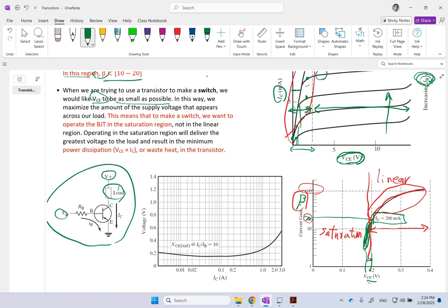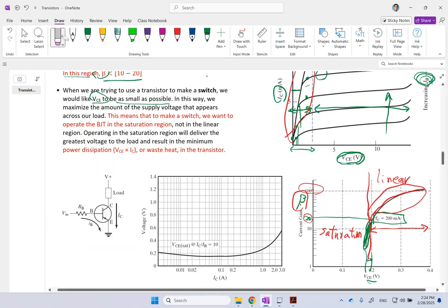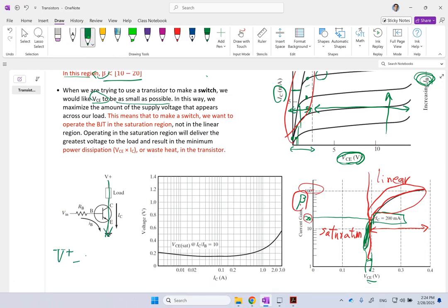You see that you're doing a low side switching with an NPN transistor. And if you look at this path here from V positive to 0, you can see that V plus minus VCE, correct, minus V of load, of course, is equal to 0.